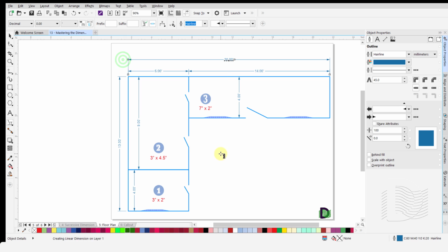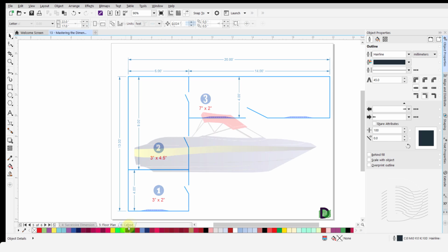Left-click once to complete and display the horizontal dimension of each room as individual segments, as well as the combined horizontal dimension for both rooms. You will note that the dimensions hold true to the custom scale we set in the Options panel.